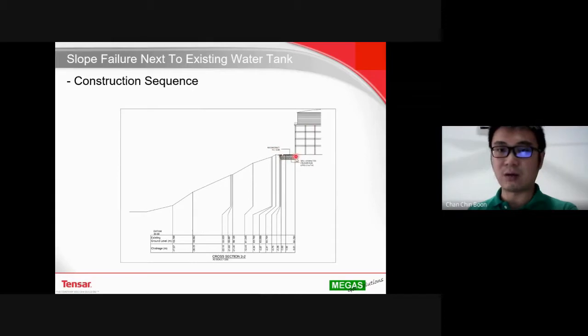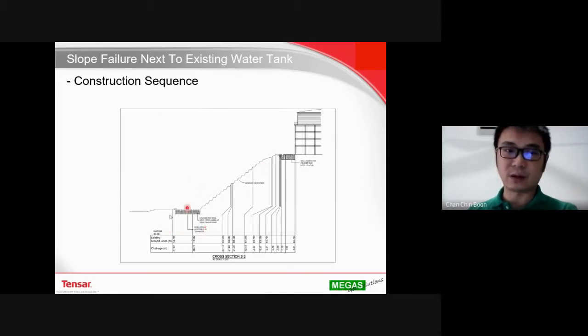By excavating now, move away the loose soil, then we put in the geogrid, and we extend it a little bit outside so that we can connect the geogrid to form the slope in front of it later. So we first complete this part, so the top is all compacted and firm, and then we excavate to remove the loose material partially at the top, fully at the bottom here, to carry out the replacement. Replacement, construct the wall, layers of geogrid being installed, followed by the slope.